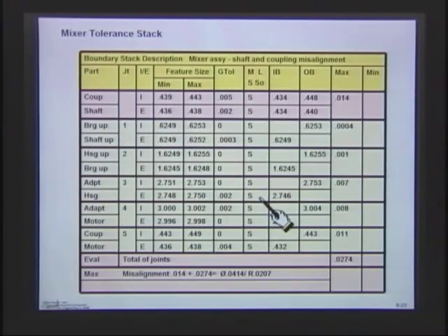So nothing would change there. But if you're working with other cases where you have a maximum material condition modifier, you might take a look at rechanging some of those. You might take a look at least material. Now, least material, generally the stack won't change. You'll end up with the same end result. The only thing is you'll get a little bit extra tolerance as the feature departs. So if you remember earlier, I showed you some of the places where you could take a look at that.